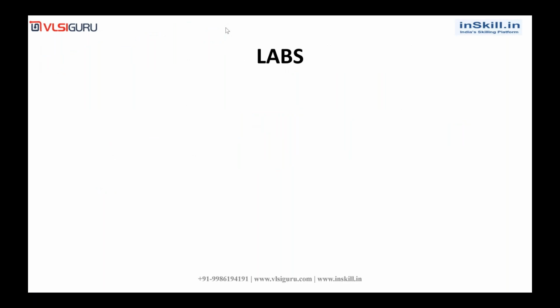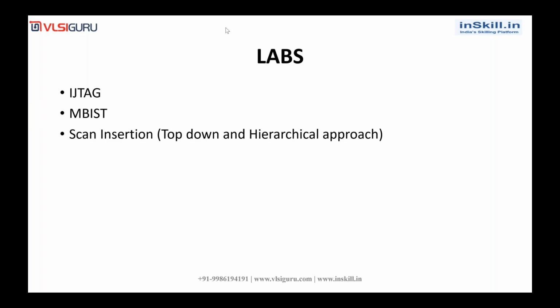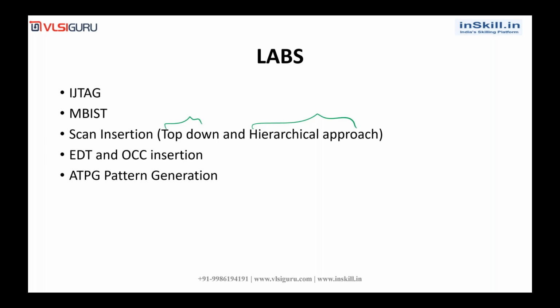So in labs, we will be doing IJTAG insertion, MBIST insertion, scan insertion. There are actually two approaches in scan insertion: one is the top-down approach and the other is the hierarchical approach. We will cover both these approaches. EDT and OCC insertion, ATPG pattern generation, ATPG and MBIST simulations. So all those things we will be covering in our lab sessions.